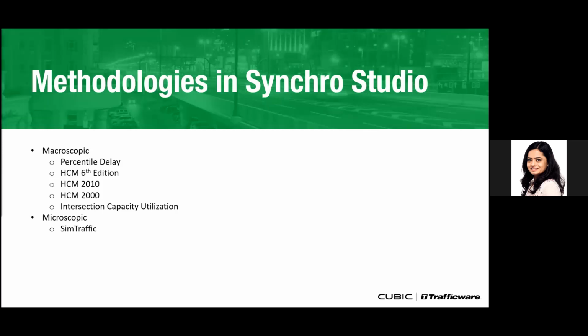Now, Synchro's companion model, SimTraffic, is a microscopic model, right? This is also one of the methodologies you can find within Synchro Studio, where each vehicle is tracked individually, and the operation of every vehicle is modeled for each slice of a second.